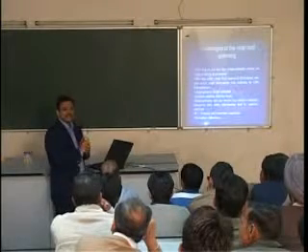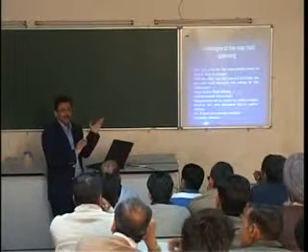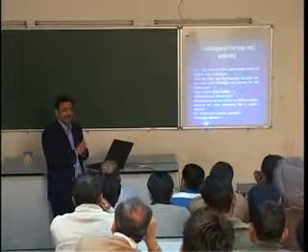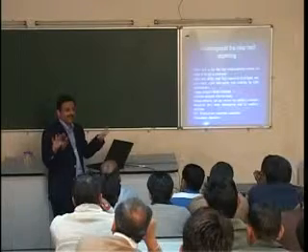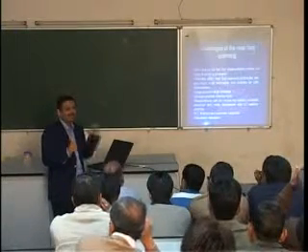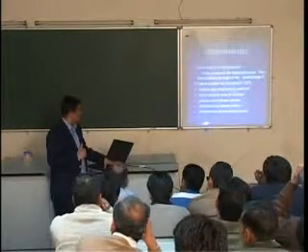Outdoor reflections become very prominent when, as I mentioned yesterday, we have to carry out a 30 dB cross pole measurement. That means all the signal levels in that area should be less than 30 dB, and only then can you pick up the signal of your antenna, which is 30 dB and better.